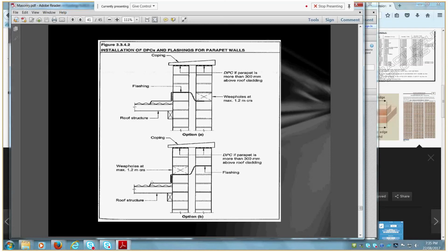You can have a box... how high it has to be. Yes, everything. Basically, square meterage of the roof. Yeah, and the rainfall intensity of the area. But basically with your box gutters, like your flashings, it's best to be conservative, make it much larger than what you really need, and also have a larger slope on there than what you really need.